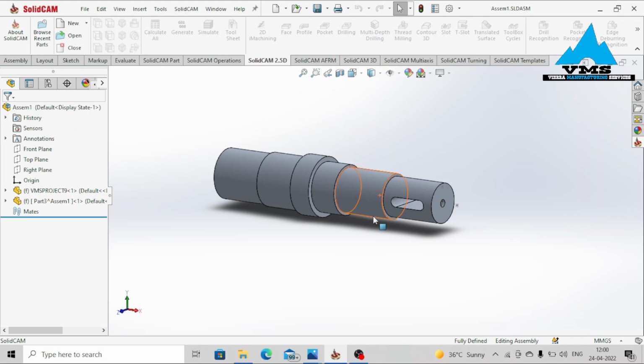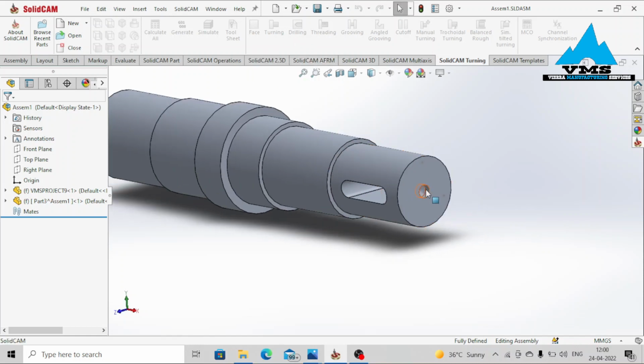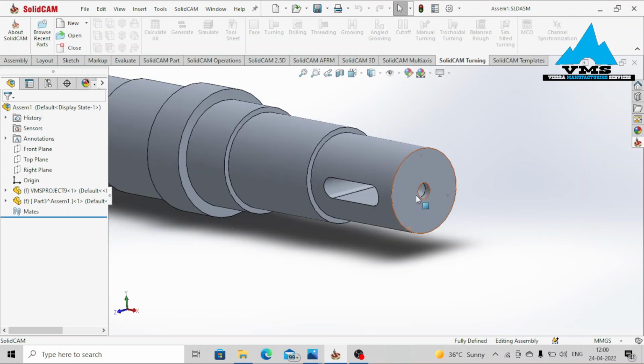So what is actually mill-turn? A mill-turn is a CNC controller that has both turning operations and some milling operations. Looking at CNC turning, we got operations like turning and drilling, and this drilling operation only acts within the center. Unlike in milling, where we could make holes at the center or at the edges, the location doesn't matter. But with this drilling operation, you must be at location X0, Y0. It's mandatory. You should be at the center. We also have threading operation and grooving operation. These operations work only with a CNC turning system.